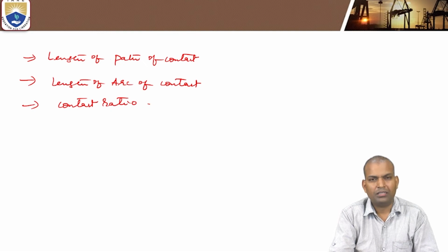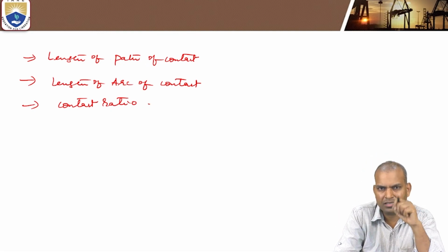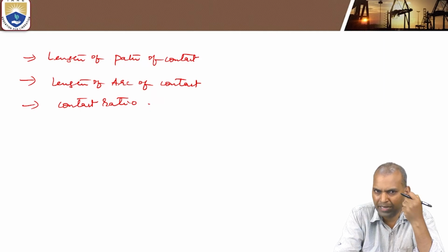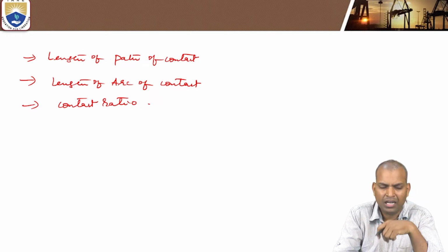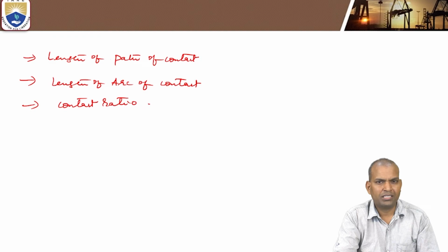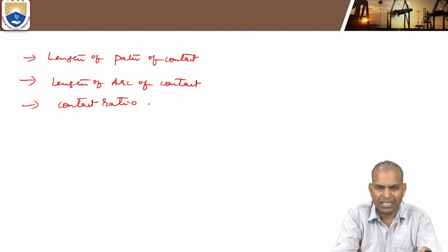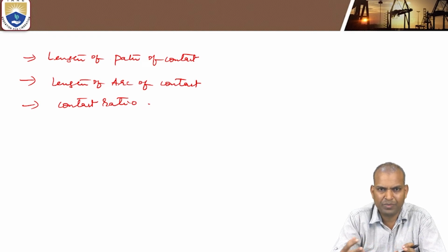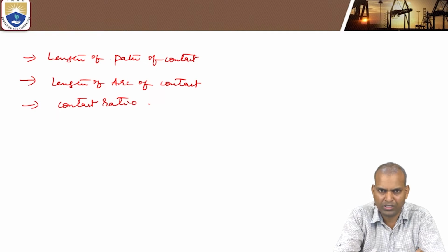These all matter for effective performance, or better torque transmission, between the two wheels, that is the gear and pinion. A larger wheel is known as a gear and a smaller wheel is known as a pinion. For effective grip, unless there is proper meshing, there will be chances of slipping between the two wheels.